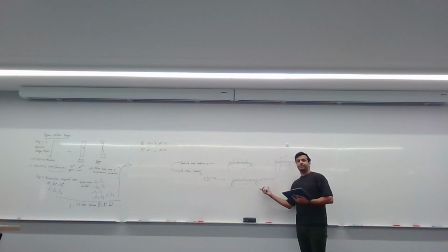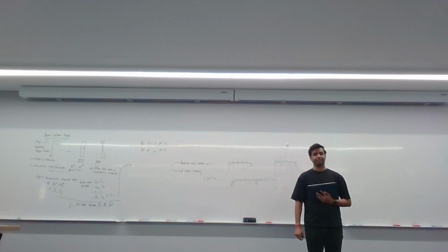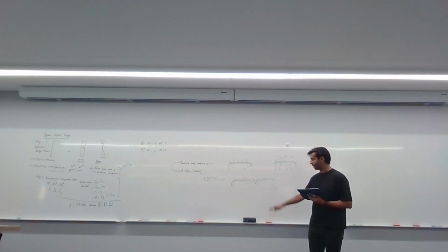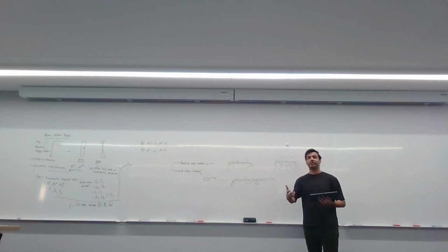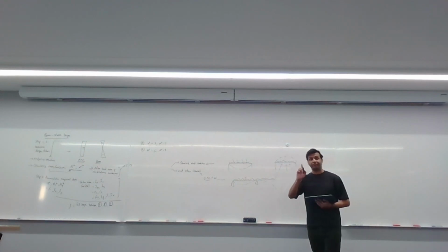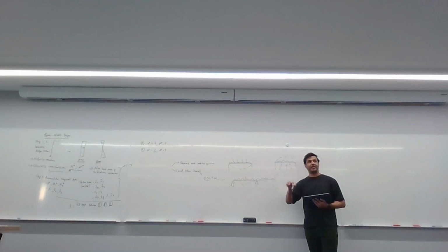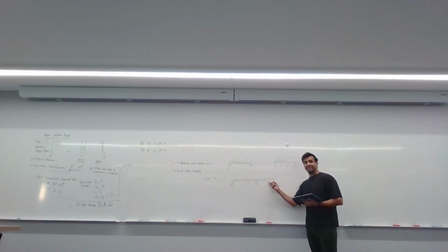This side here, where's your compression flange? The top flange or the bottom? Bottom. Compression is on the bottom flange. But for a cantilever segment, what is the critical flange? Compression or tension? Tension. The tensile flange is the critical flange for a cantilever segment. So for this segment here, the top is in tension.